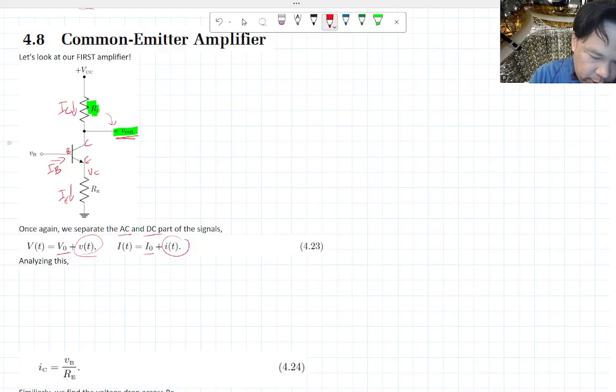At this point is the voltage at the emitter, right? When the current travels through this emitter resistance, it goes to ground. This is a good starting point because it's very simple: the voltage at the emitter is going to equal I, the current through the emitter, times the resistor at the emitter, because you're dropping the voltage to 0.